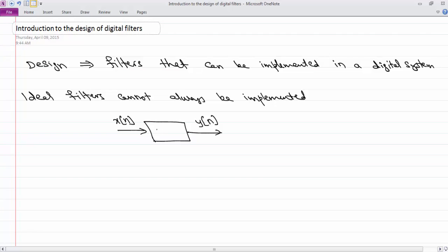So at the end of the day, you realize that you need a filter, H n, which is an ideal low-pass filter. So what is an ideal low-pass filter? Well, it has a discrete time Fourier transform, which is given by 1 for absolute value of omega less than or equal to some cutoff frequency omega c, right?